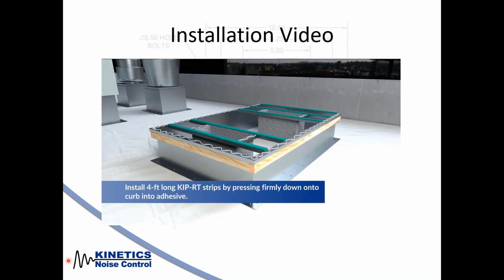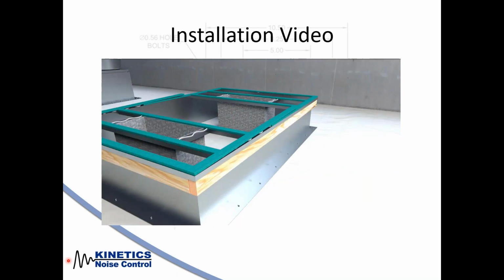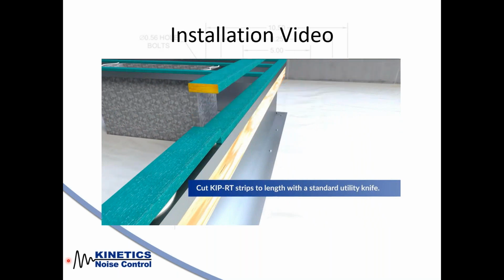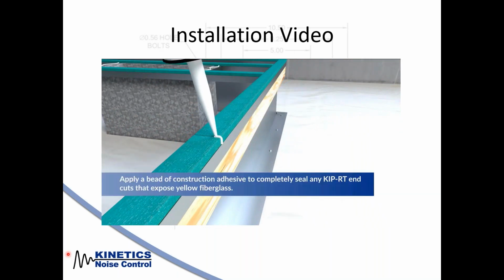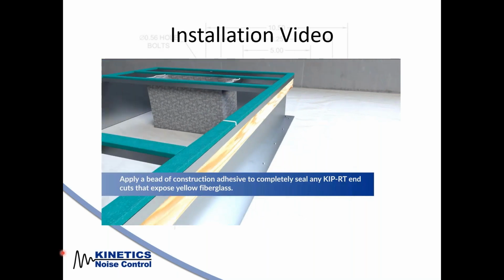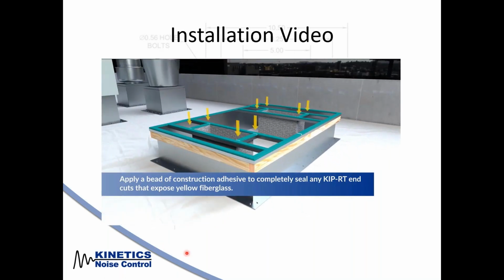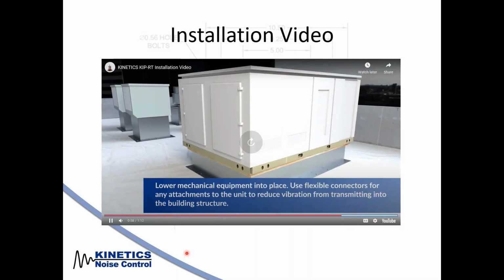When you have a spring rail, you have to lock those internal springs out, because a spring on top of a spring makes the vibration worse. But when you've got a spring working in series with a piece of pad, that works really well. So this is a good way to offer a really nice, cheap solution anytime someone's looking to get rid of the spring rail.